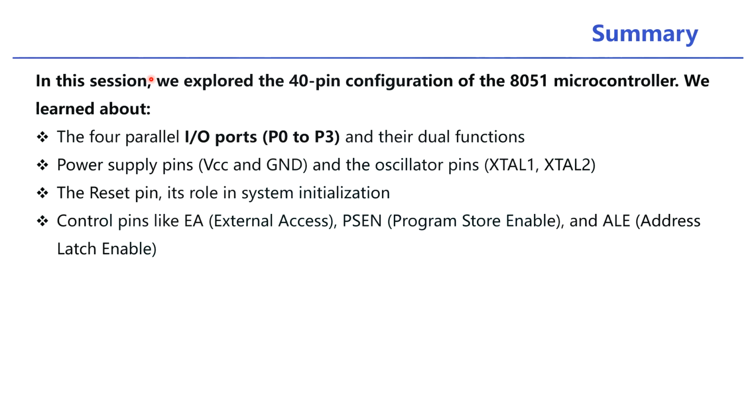Now we come to the summary. In this session, we explored the 40-pin configuration of the 8051 microcontroller. We learned about the four parallel ports, that is P0 to P3 and their dual functions. Power supply pins VCC and ground, and the oscillator pins XTAL1 and XTAL2. The reset pin, its role in system initialization.